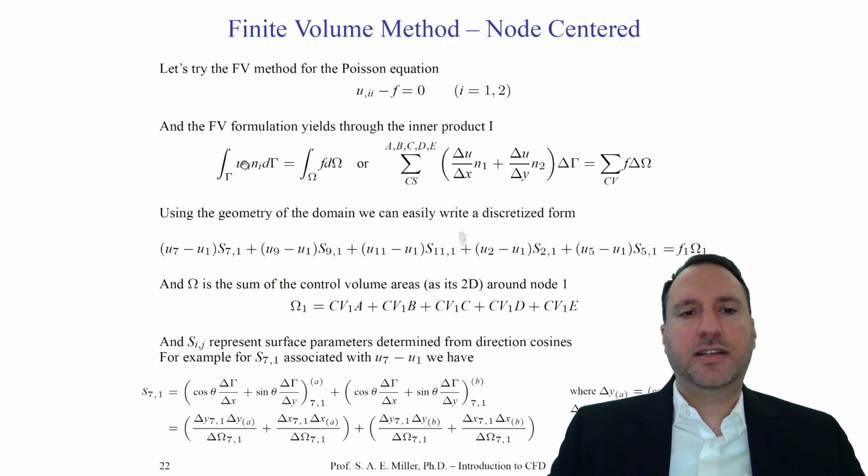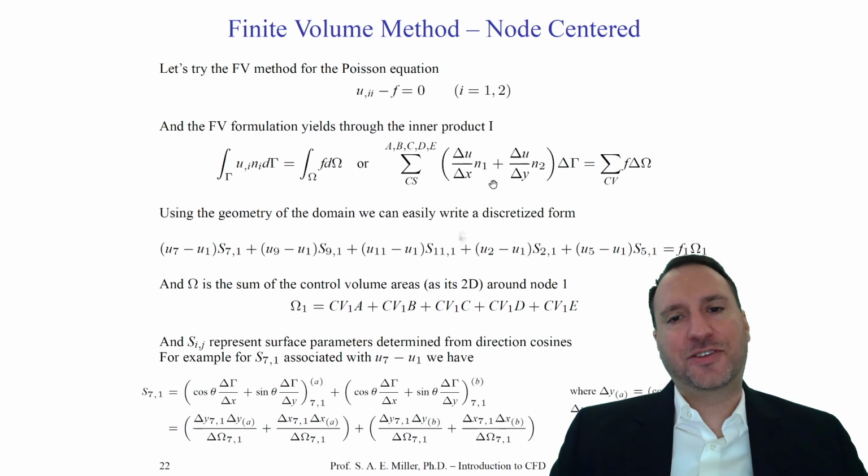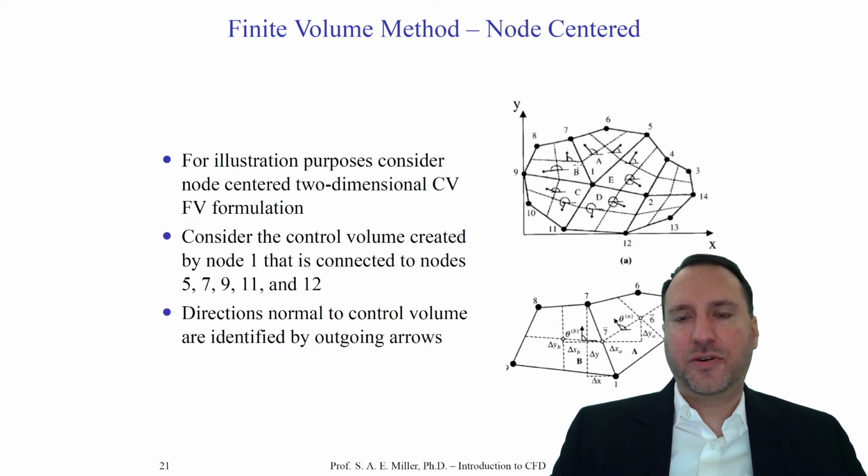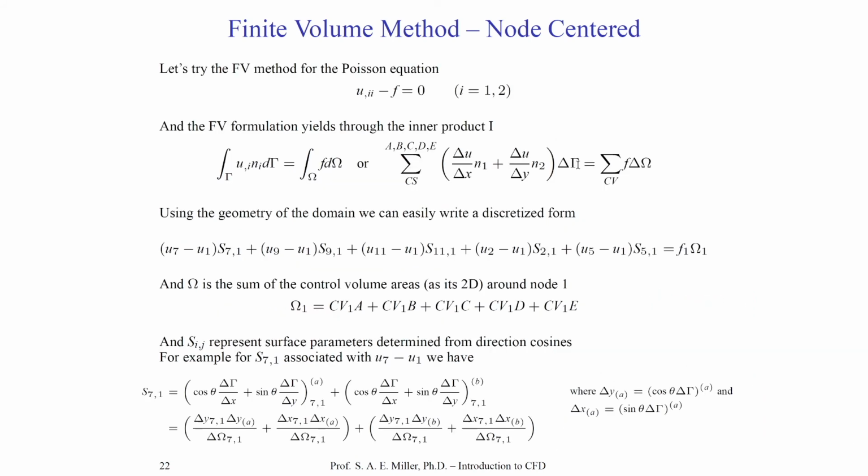We discretize the integrand of the integral, and we'll get delta u over delta x of all the normals plus delta u over delta y of all the normals. So this is the change of velocity between the volume we're looking at and the neighboring volumes over each control surface. Delta y and delta x, of course, are the approximations of the distances between the centers of each volume. It's so straightforward and geometric. You can look from this slide on the right to the next slide and this equation, and you can match it up one for one. Try it out. It should be super straightforward.